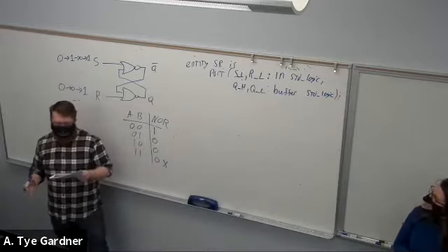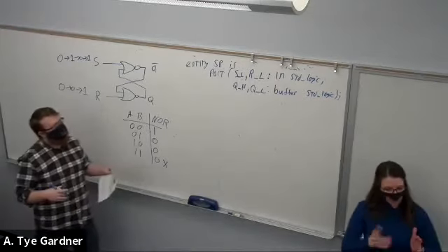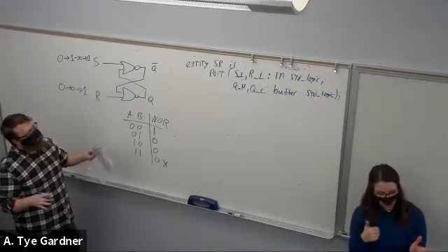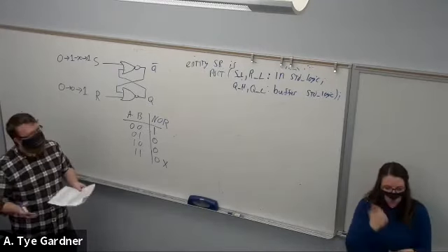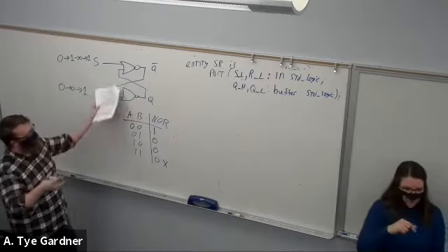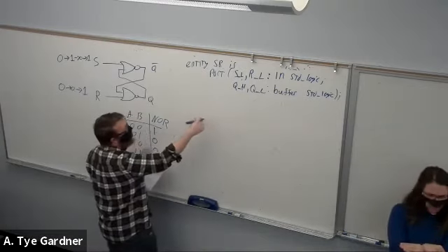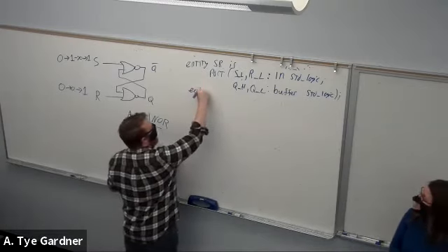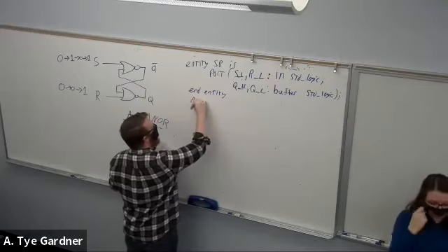So that buffer allows us to avoid the issue, that error that we know is coming, right? You can work around it by creating intermediate signals, but let's focus on using a buffer because that's the new idea for you. We would then have the entity and the architecture.